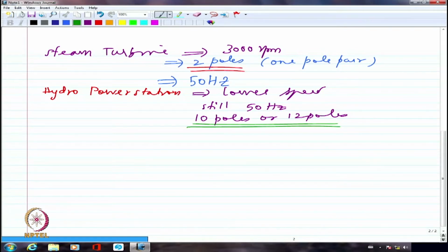And if I am talking about higher speed, with a large structure rotating at a very high speed, then if you look at the linear velocity around the peripheral surface of the rotor, that is going to be enormously high. So generally you will have some kind of deformation if the rotor has a protruding structure like this.